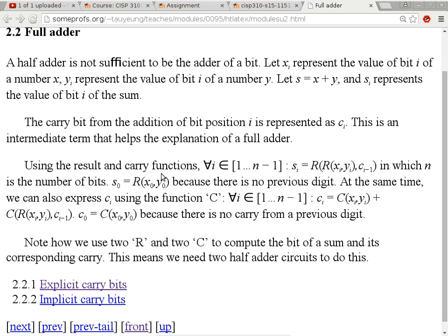So this is the propagational delay of one single gate. When you're talking about a half adder, it has more gates and more transistors in it, so there's a propagational delay integral to a half adder. When you look at a full adder, I cannot finish this calculation until this half adder and this half adder are both done. Does that make sense? So I have some additional propagational delay because of this. Now, when you stack up these full adders, each one depends on the previous one because the carry bit comes from the previous one.